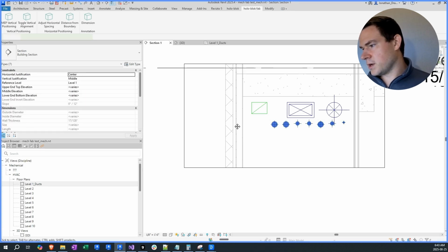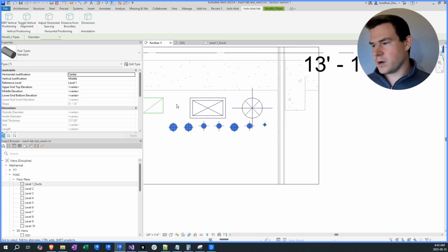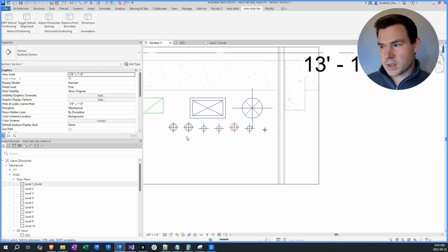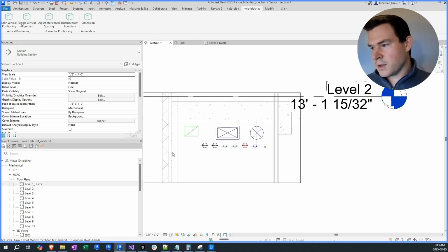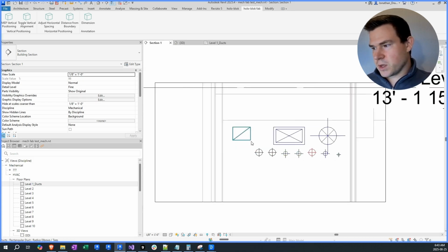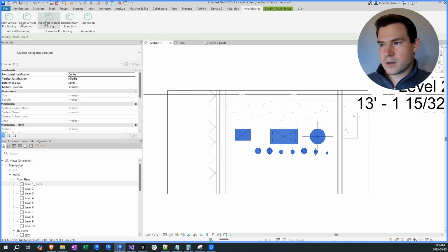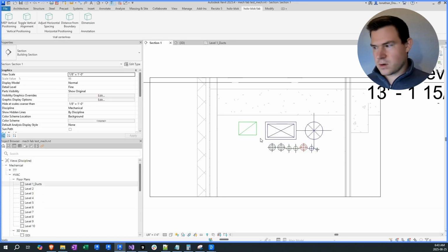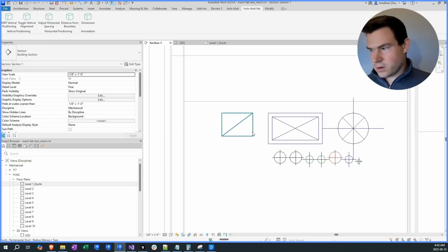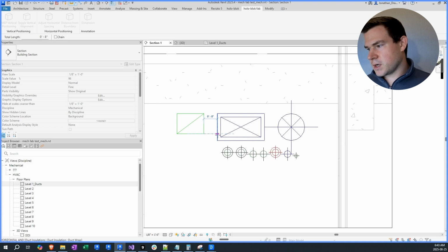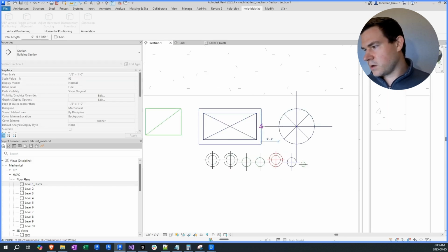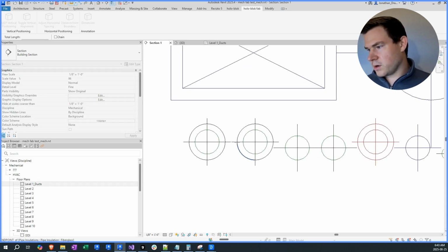We can also toggle the positioning of those pipes very easily, where depending on whether we have the support above the pipes or below, we can very easily adjust for that. But we usually need to tighten these up quite a bit for constructability, and tighten up the ducts a little bit as well. So now what we can do is select all of these and click on adjust horizontal spacing. Right now we have the value set so that there are 8 inches clear between ducts. This can all be configured. And 2 inches clear between pipes.